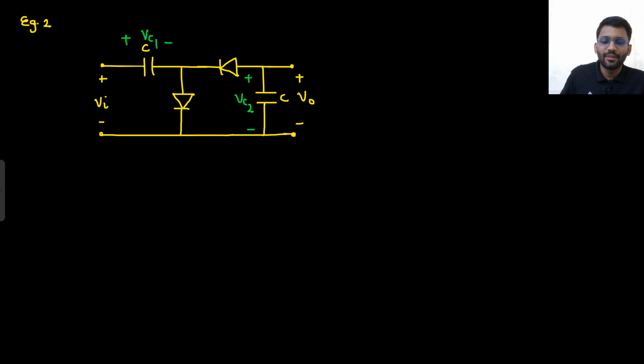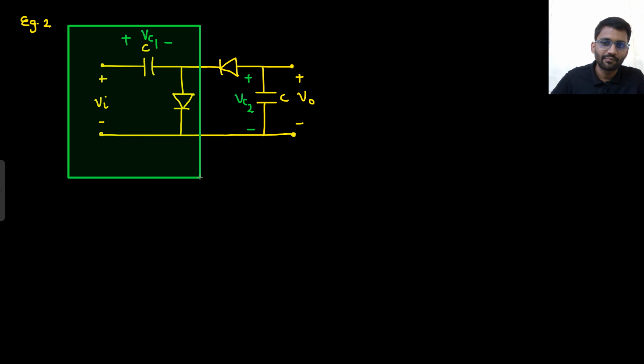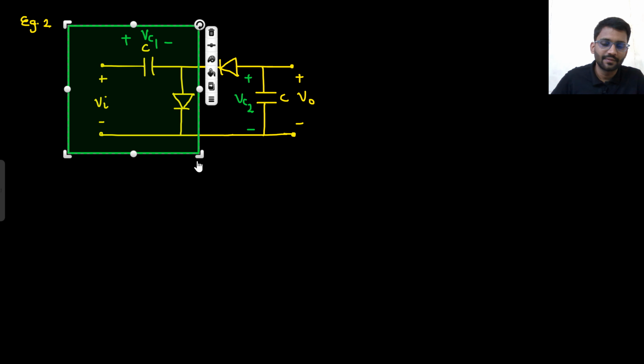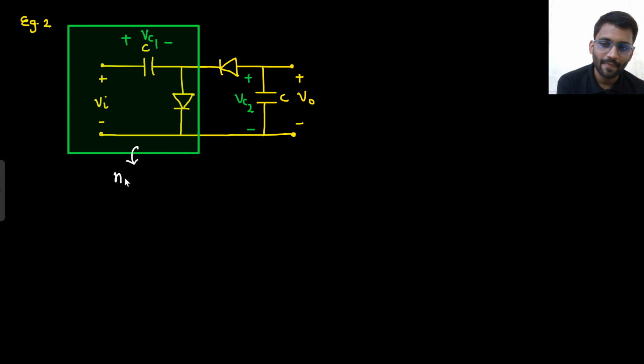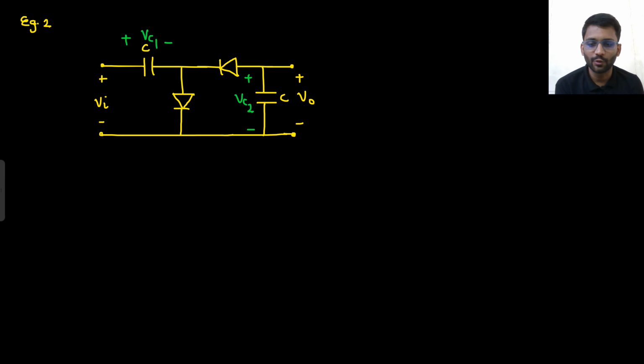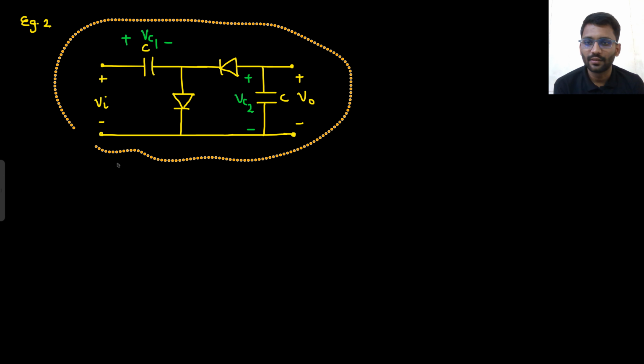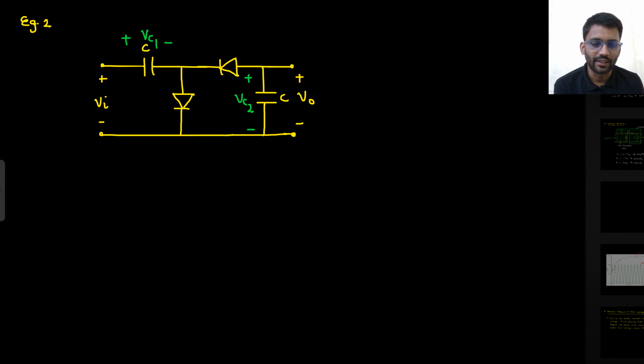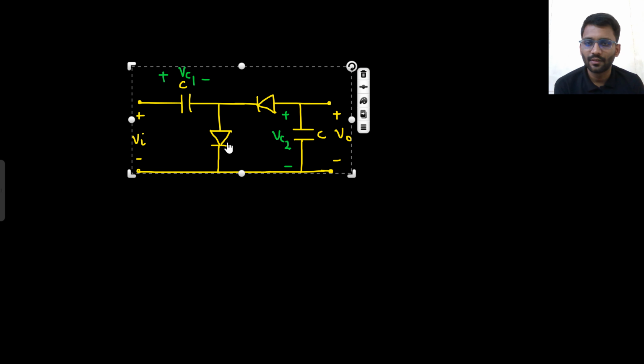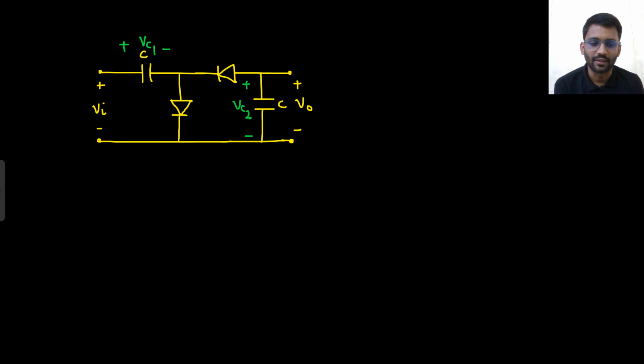This one. Tell me the output first, because here you can see two standard circuits. What is this circuit? Negative clamper, right? This is negative clamper. Before writing this, let me copy this circuit because we will be solving it with two methods. Method 2 we will be using on the next page only. But first let's solve with method 1.